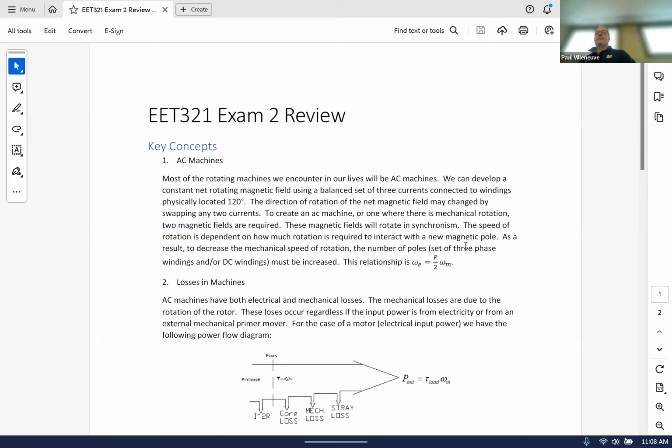When you say set of windings, is that all 3? All 3. So you need 6 sets of windings, yep, or 12 wires, right? And in and out counts for that. So yes, we're talking about 3-phase machines. We want to make sure that we have a balanced load as much as possible. So we're going to put a set of 3 windings every time we're adding a pole pair. We're not going to add 2.